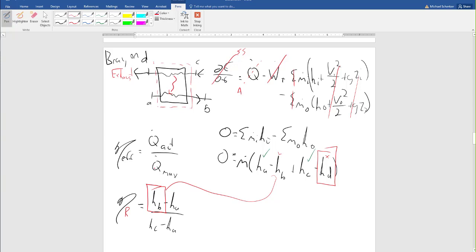I could give you an opportunity to better demonstrate your understanding of thermodynamics if I tell you maybe there's 10 kilowatts of heat loss that comes out of this thing. Then this is not adiabatic, because this is only adiabatic if none of this heat transfer goes across my control volume.